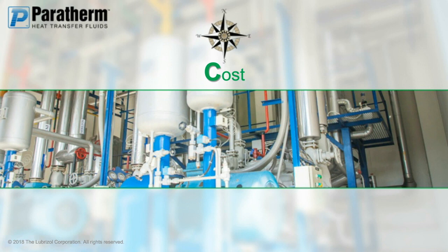Next, we're looking at process controls versus fluid controls. And that's in quotations on purpose, because fluid controls are typically very limited. By that I mean the additive packages that you look at, or a higher flash point fluid. Someone's really concerned about flash point, decides to buy a fluid that advertises a 650-degree flash point, right? Unfortunately, a lot of times that kind of fluid is going to cause more long-term detriment to your system than one that doesn't. So you're also typically going to pay more for those. So process controls are going to be more important, more effective, and long-term less expensive.